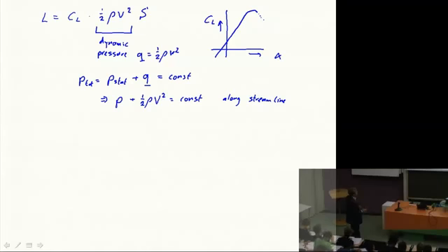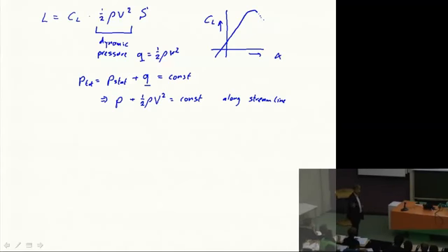And if along a streamline this is constant, this also means that if you put your hand outside a car window or plane window, and you stop the flow, then you basically, at your hand, make the speed 0, and you will feel the total pressure. And on the other side of your hand will be the static pressure of the atmosphere. So basically the net force that you feel at your hand is the dynamic pressure.